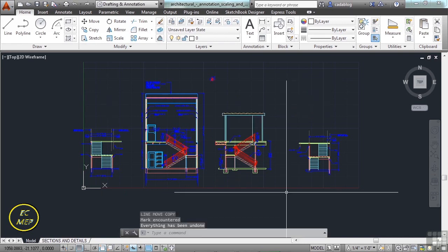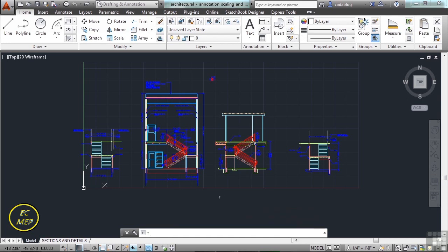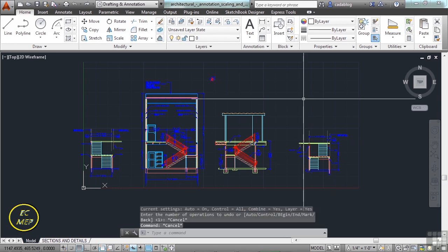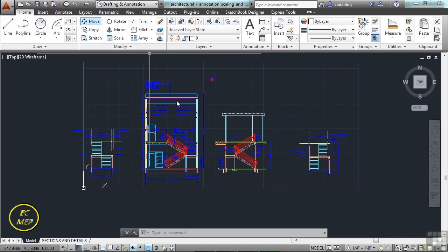That's kind of cool. You can go all the way back to the very beginning. You can set up some controls, go back to the beginning, just go back, make a mark, etc. But honestly, all you're really going to need is the Control-Z, or just the letter U for undo, or use your tools up here in the quick access toolbar.